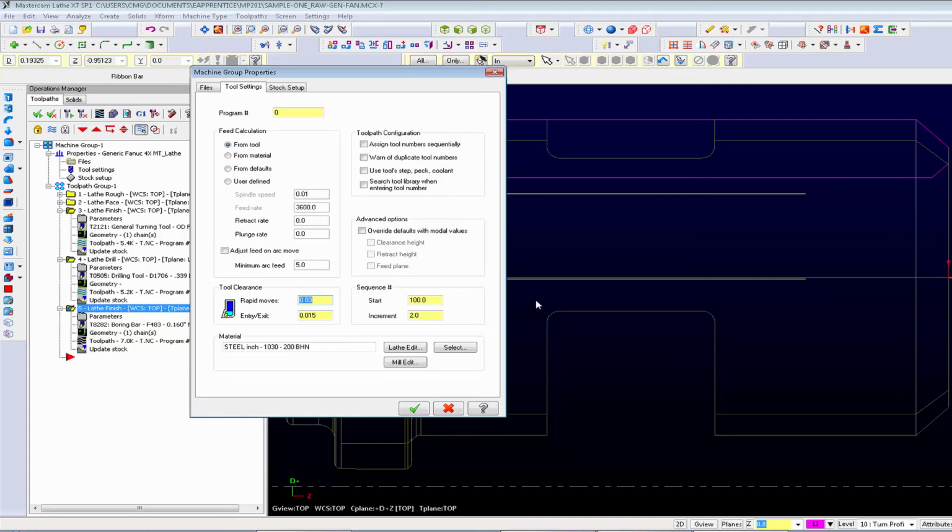So if you're working on a real tight bore with a tool that's very close to the bore diameter, a lot of times I will go in here and make this like 3 thou, or sometimes even 3/10, if I really need to get my tool in there. I forget what the minimum is. Let's say 3 thou here, and you may even have to do this with your entry-exit tool clearance, looks like 1 thou is the minimum. Okay, so just be aware of this one.